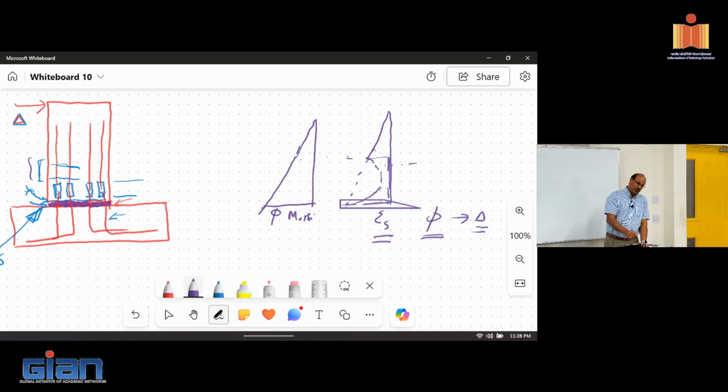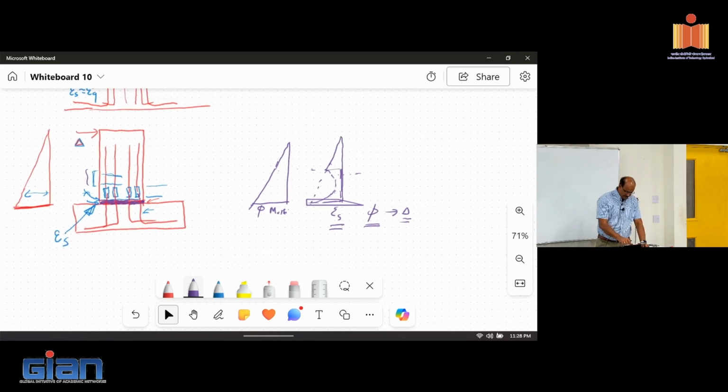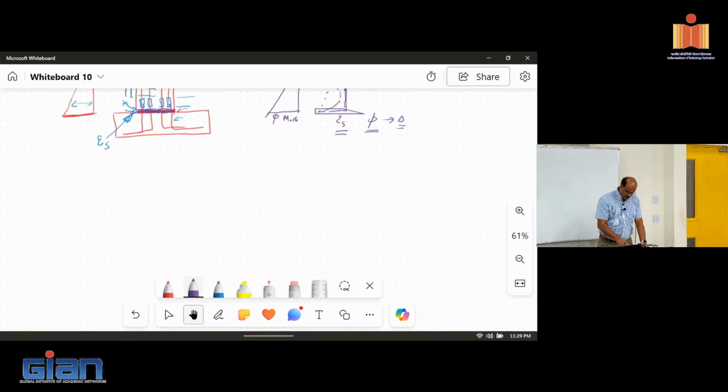By forcing the precast wall to behave like a cast in place, we are achieving some kind of equivalency in terms of detailing, but I want you to know that it does affect the wall behavior as well as the force displacement to some extent. That should be given consideration. I'm not saying one is bad or not. Okay, let me just move to the next option.